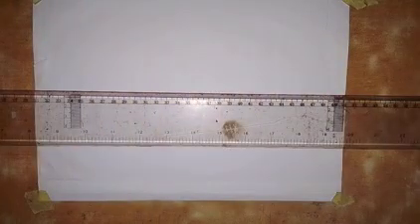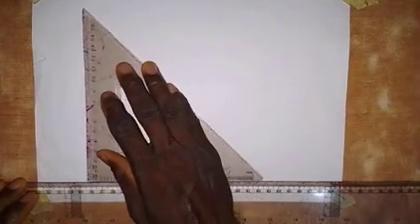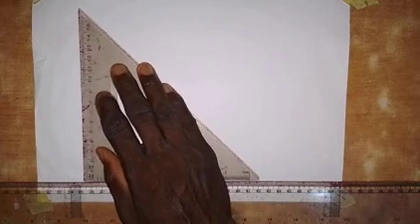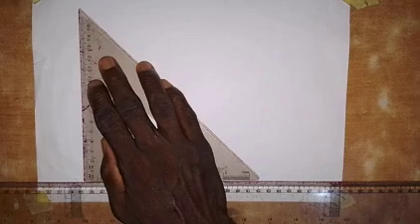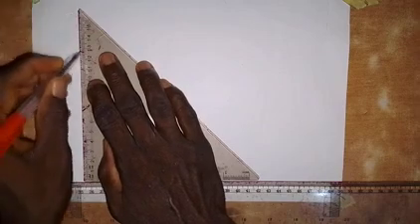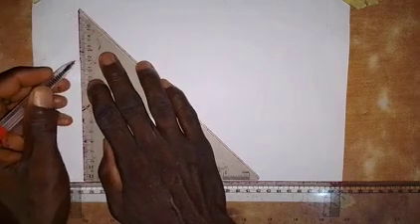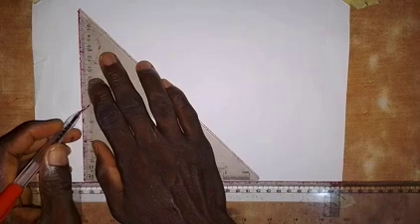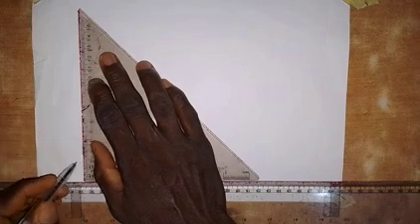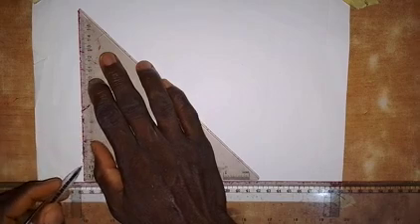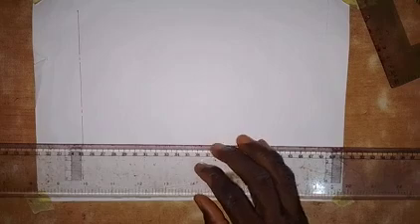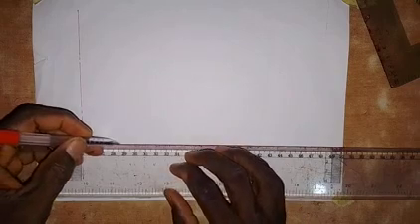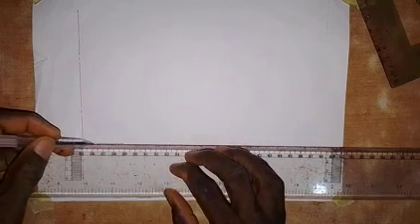The first thing that we are going to do here is to draw a vertical center line. You can start with a horizontal center line if you like, there's no problem. I'm not mandating that you start with a vertical center line. A center line is drawn with a thin long chain line. As you can see here, you draw a long line, a dash, a long line, and a dash. Okay, so we draw the horizontal center line like this.